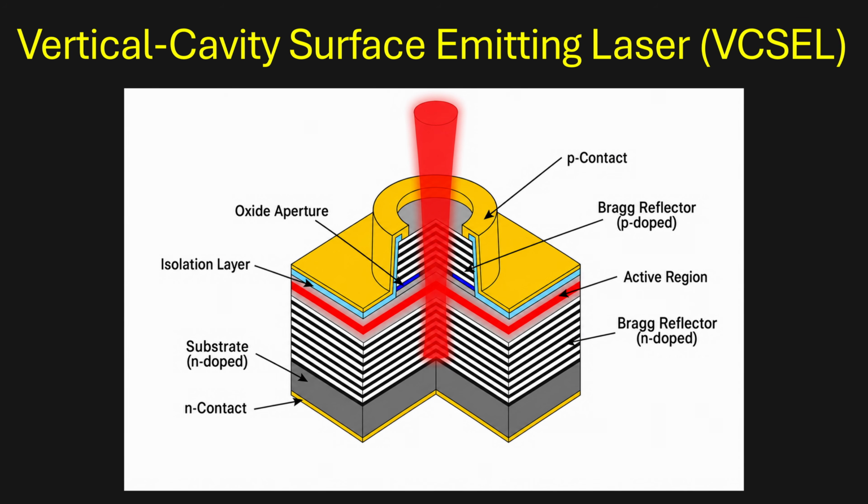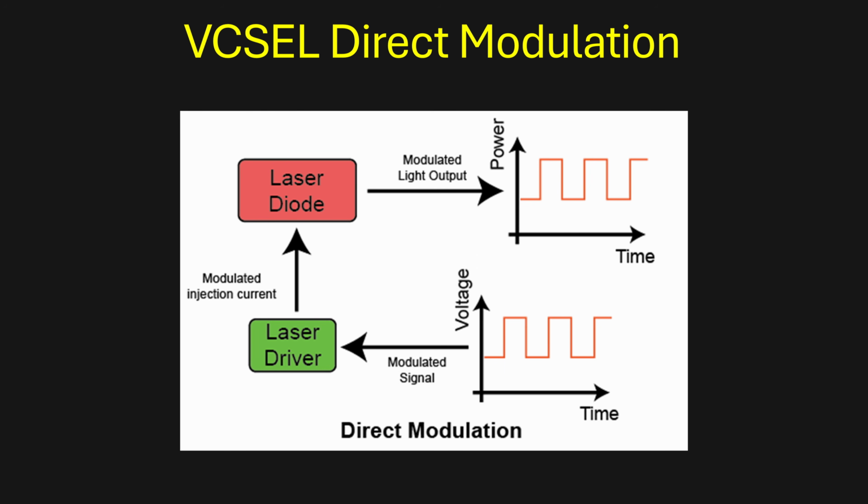The vertical layering of the VCSEL makes manufacturing and testing simple and inexpensive, especially for wide aperture VCSELs, so these are the most common choice for short distance MMF. The short active region also allows the photon population to react very quickly at low currents with direct modulation.